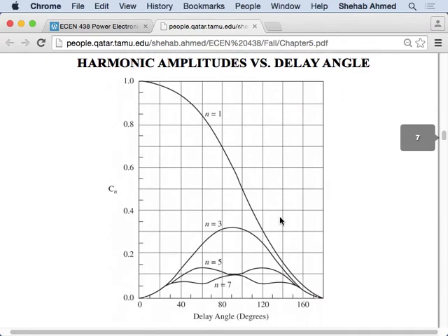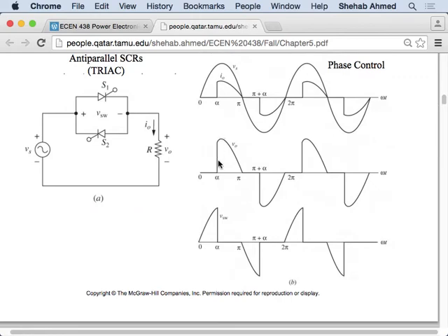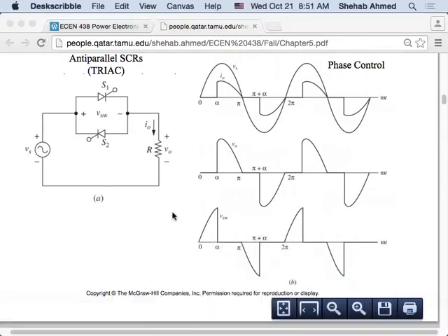Yes. So if we have a low-pass filter for that circuit, what would the output look like? If you have a low-pass filter, it will not allow this quick jump, right? So it will make it rise slowly. Depending on how sharp your low-pass filter is, you will eliminate some of the high frequencies. How much of the high frequencies are you eliminating? Everything beyond the 5th, or everything beyond the 7th, or everything beyond the 100th? That depends on how sharp your filter is.